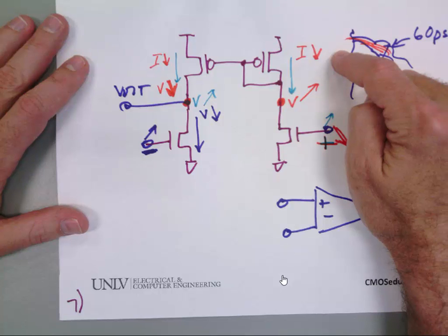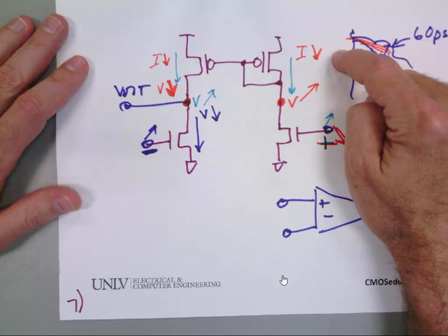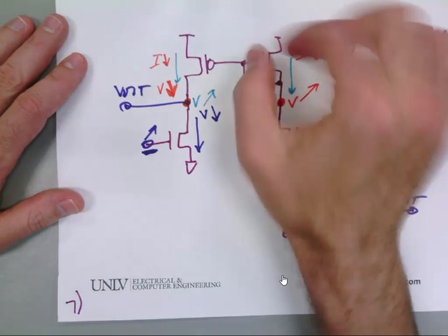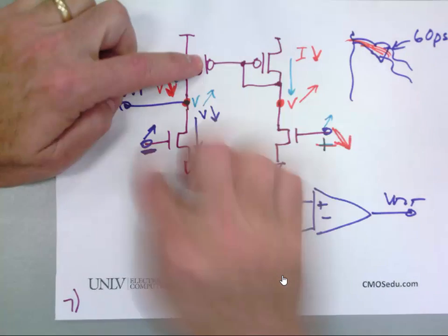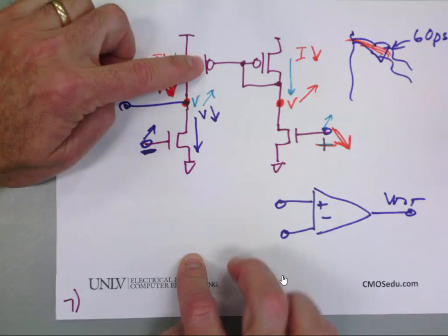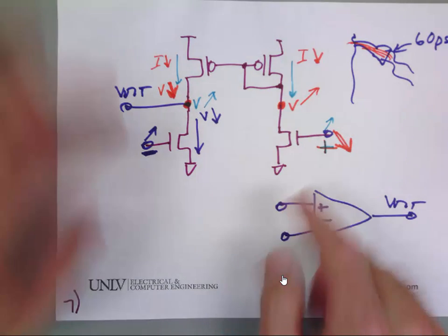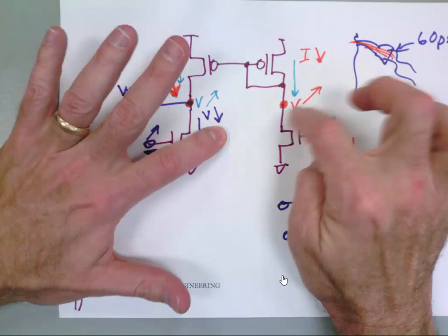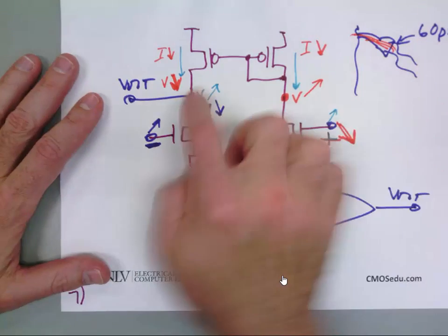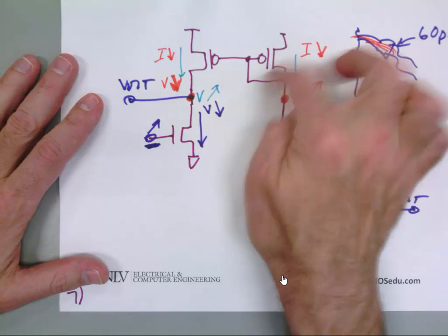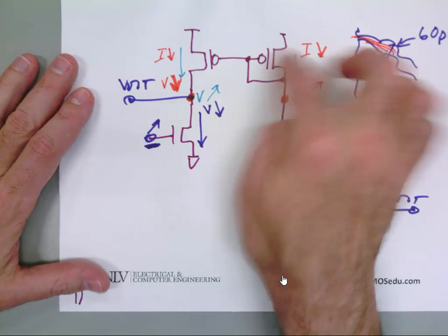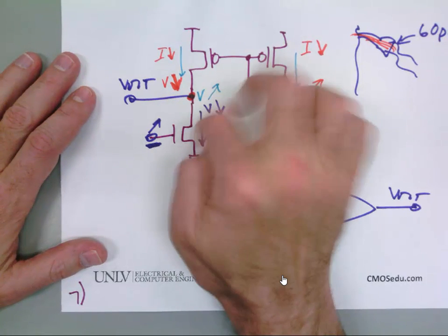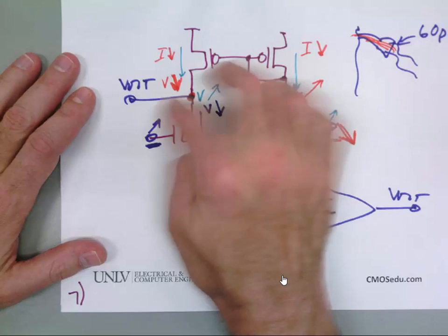That increase goes up. When you have an increase in voltage, you're going to end up closing that current. Then the current mirrors over to here, so that shuts off, but this one stays on the same amount, so it pulls it down. This is a diff amp, but you generally don't draw them like this. So if this side goes up, this side goes down, this side goes down, this side goes up. This one doesn't swing as much because it's diode connected by this, so it kind of clamps it. This one can swing a lot because it's not got any clamp. I mean, there's nothing clamping it there.